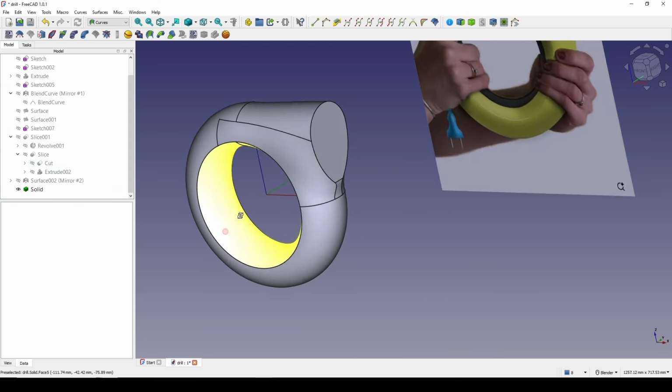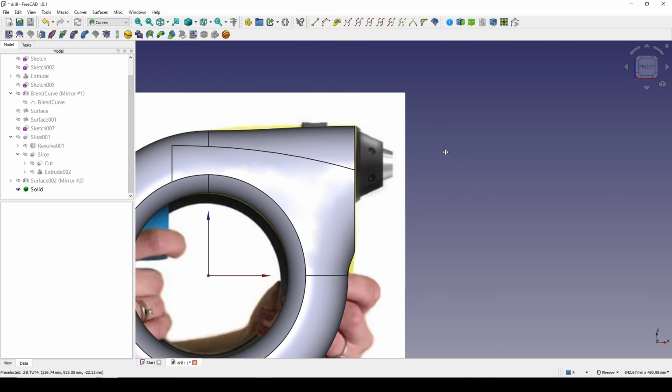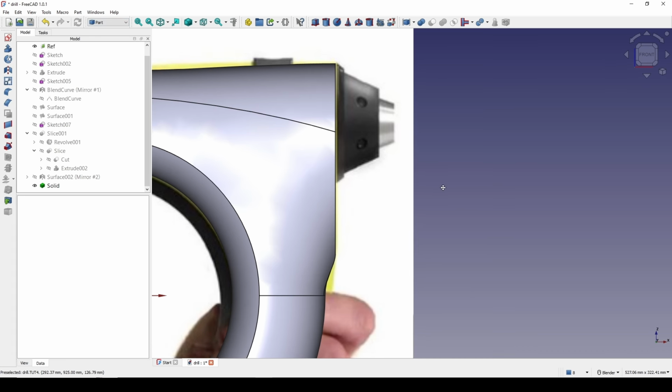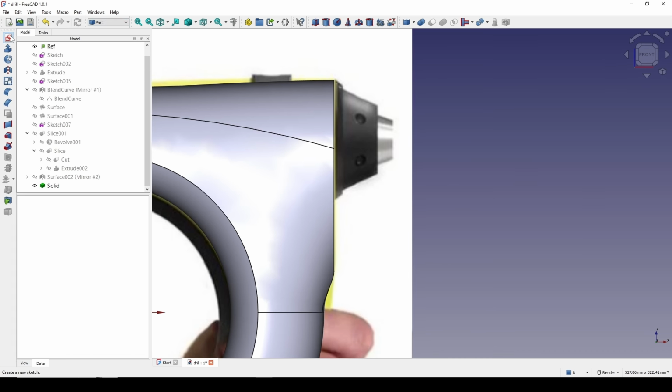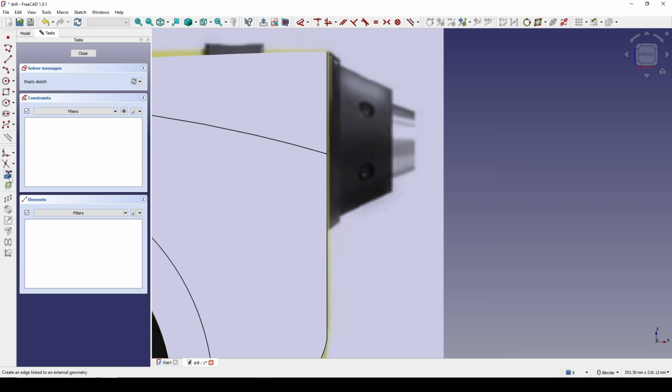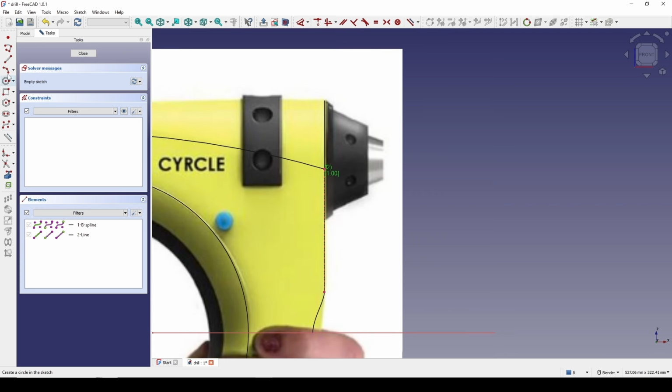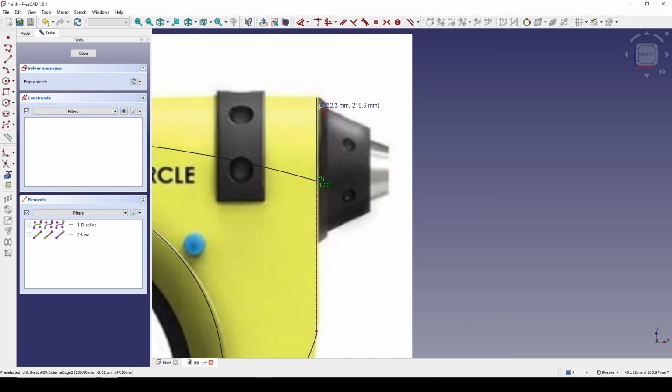Okay. Now I will create this geometry in here. So you can go to the part workbench and create a new sketch in the front view. And let's reference this one, view the section or wireframe. Reference again, let's try this one. Yeah. And I will create a polyline, and we start from here, somewhere in here, and just create the shape.